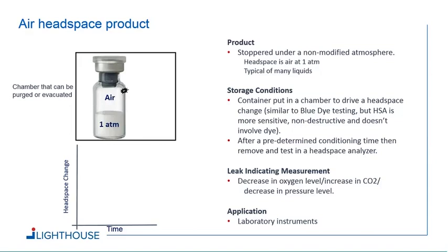Now you're doing it with gas, and it's going to be much more sensitive and will also be non-destructive when compared to blue dye testing. So you define some vessel cycle, a conditioning time, and then you remove the container and see if you've been able to trigger a change in the headspace condition.